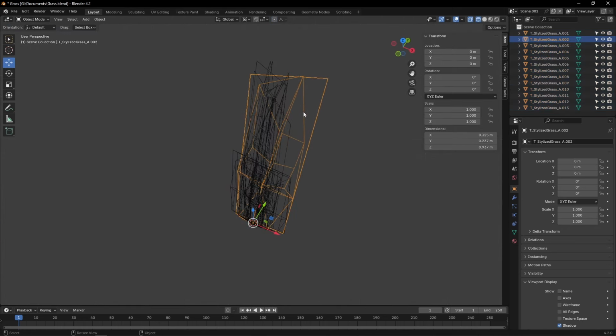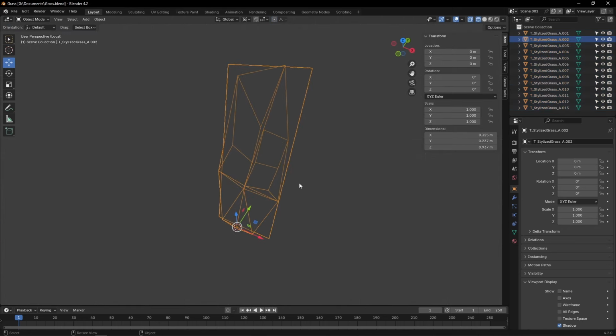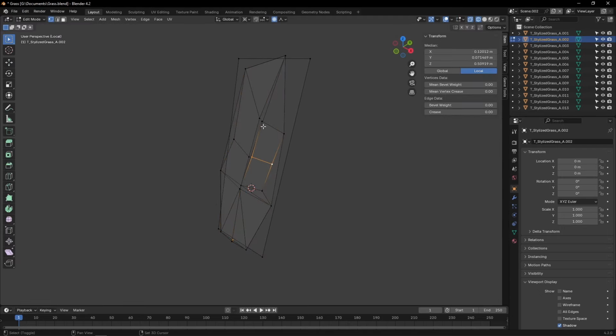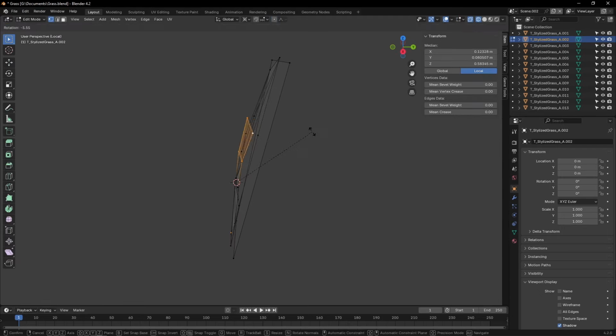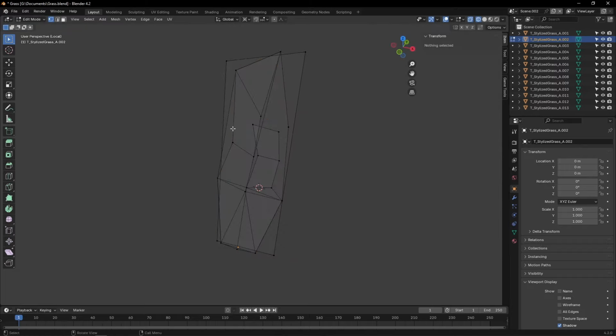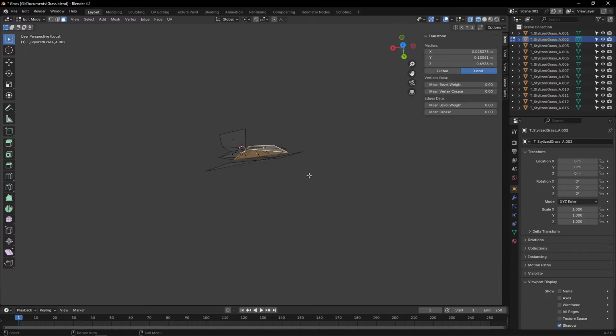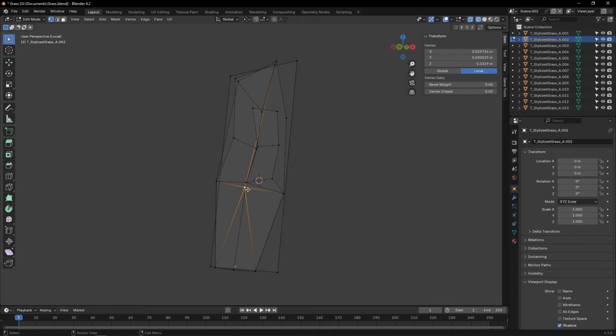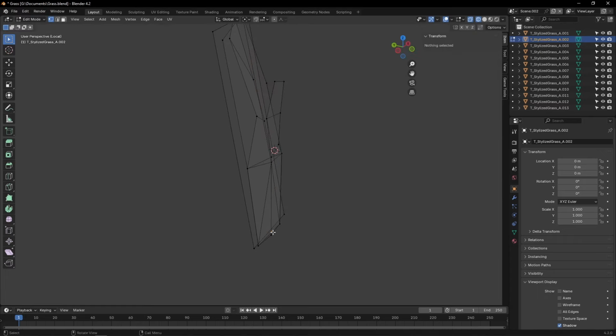Finally, I'm going to isolate one of these objects and see how I can make these cards look a tiny bit more appealing. The goal is to try and make these cards have the maximum amount of pixel coverage when looked at from any angle. A flat card being the worst case scenario. Look at it from the side and it disappears, right? And so that's where being a bit smart with the way you create your cards is going to help.